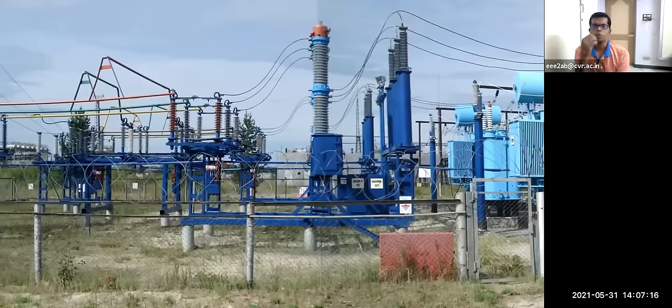Hollow tubes, aluminum tubes or copper tubes. Generally, copper conductors are very costly. Most substations go for aluminum rods, which do the same work. There might be a small percentage difference in conduction, like 0.1 to 0.5, but aluminum does the same work as the copper conductor. You would have to install copper conductor, but because copper is very costly, we mostly go for aluminum rods.